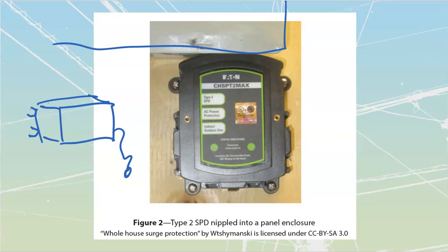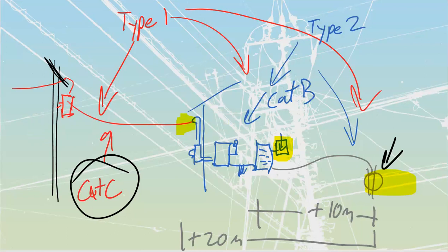Type 1 surge protected devices, they don't have any pictures inside of here, but they're going to be bigger ones, usually supplied by the utility, because I know that anything between here, the weatherhead, and over here, that's all owned by the utility. So they'll be the ones to have that there if required. Usually not for standard residential applications, but for commercial or industrial, we could absolutely expect to see them. All right, that is the end of surge protected devices.